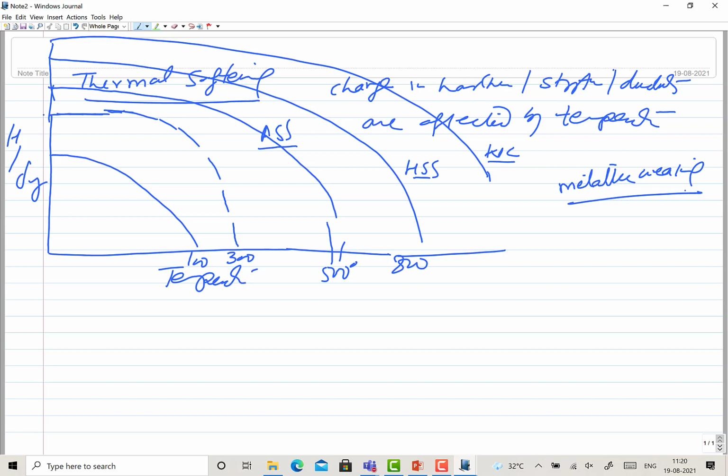At high temperature, accelerated creep and the factors governing cross slip and grain boundary sliding all contribute to easy deformation. So metal tends to get softened. This is the simple point I want to make.